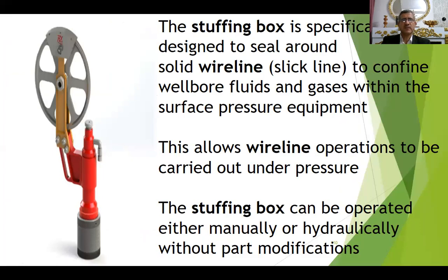So if it is leaking, or before we wait to get a leak from here, we have to make sure that the packing is suitable for the operation. This allows wireline operation to be carried out under pressure. The stuffing box can be operated either manually or hydraulically without part modifications.